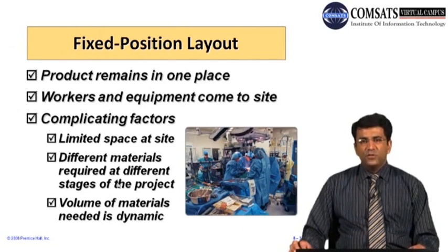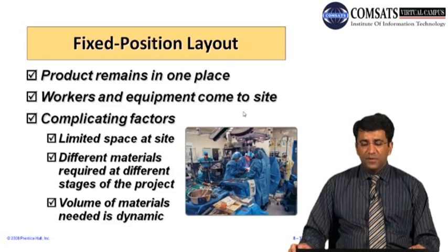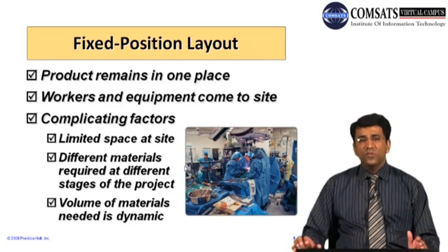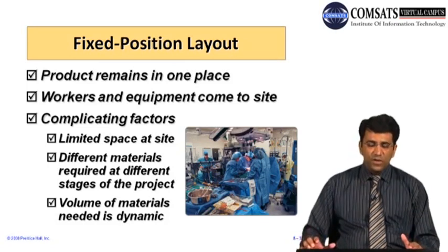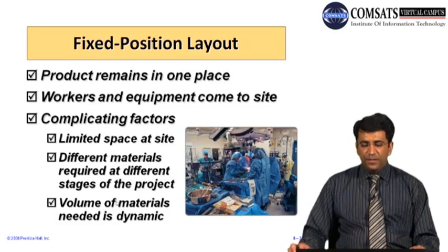The next important point of layout is the fixed position layout. Now students, these are the types of layouts in which the particular and heavy machineries are fixed at a particular point, and the product remains in one place. Workers and equipment come into that particular site, because we cannot move the heavy machinery or heavy installments, but the workers and the equipment may be brought to that particular location.